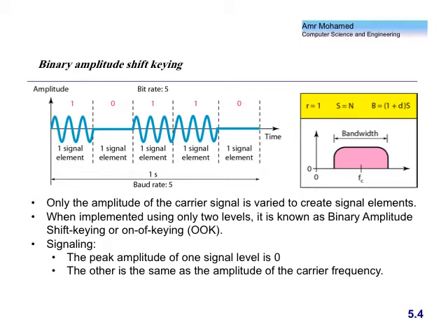So D is somewhere, again, like the C factor. D is somewhere between 0 and 1. But remember here, the D is added to the 1. So 1 plus D times S. The typical bandwidth here is 1 plus D times S, where D compensates for the imperfection of the filtering and modulation circuit at the sender side. Okay? It's something that has to be given, like C.